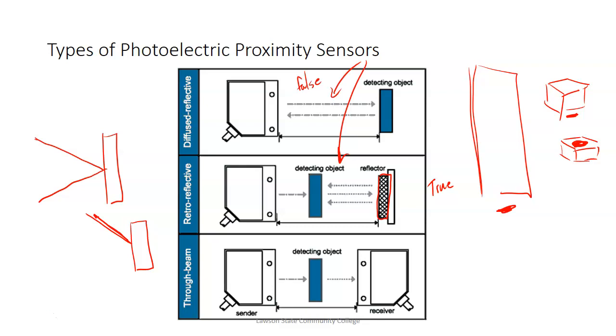One of the things they do in that class is they'll use a normally open contact, and it'll start off energized when we want it to start off de-energized, right? So they have to figure that out. That's something you'll see in a sensor. These guys will be true when they don't see something. Their outputs will be true if you're using a normally open contact, and then when the object breaks it, that's when they become false. And that's the same thing with what we call a through the beam.